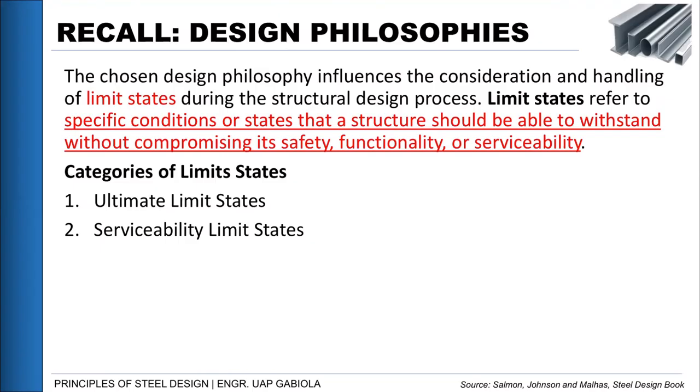And then another category of limit state is what we call serviceability limit state that we have mentioned before, deals with the overall occupancy of our structure. It means it may be the limit of deflection or cracking or vibration that our structure can withstand, and we don't want this to be exceeded also.